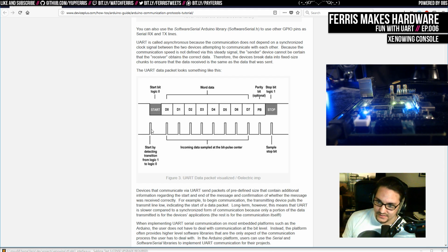Anyway, I'm probably going to make this as simple as possible and not terribly robust, because between the COM port and the USB interface, I expect things to work. So I don't expect this to be that crazy. And at the same time, this is really only going to be used to reset the system and load new ROM. So I don't really want to implement a very complicated protocol. I don't want to implement failure cases, because I can just send it again. I can just reset the FPGA. So it needs to be only as robust as it needs to be.